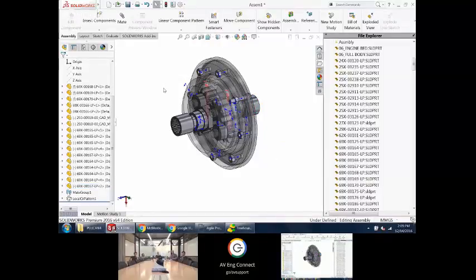Really what I wanted to show you was the smart mates and dragging from a window. Really nice tools for populating things easily. Also, kind of talking about the hierarchy of how difficult a mate is to solve. When you have to look at geometry, that's the toughest one. When you're looking at something like this where it's a ratio, it's not that tough because it's just got to do the mathematical, but it is tougher than like a coincident or concentric where it's locked into a position.